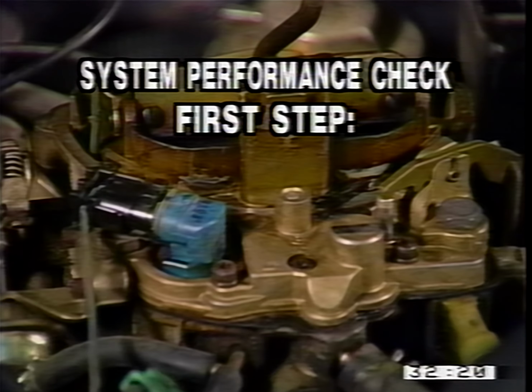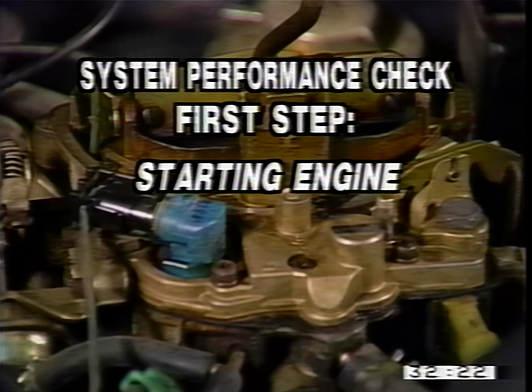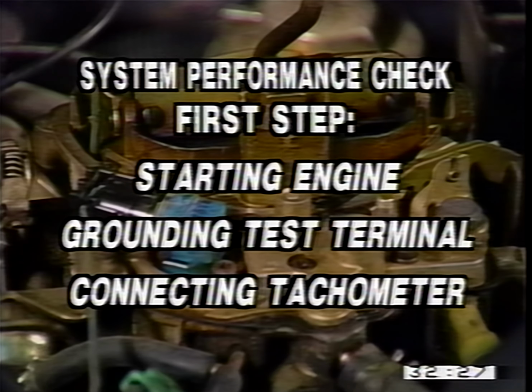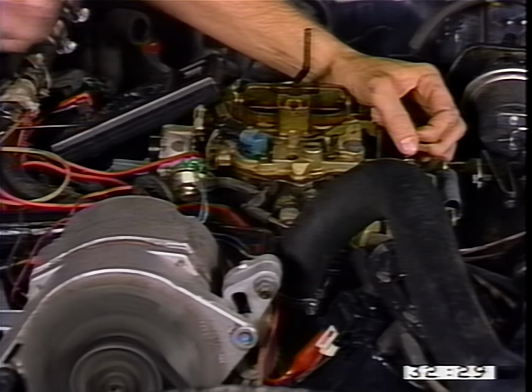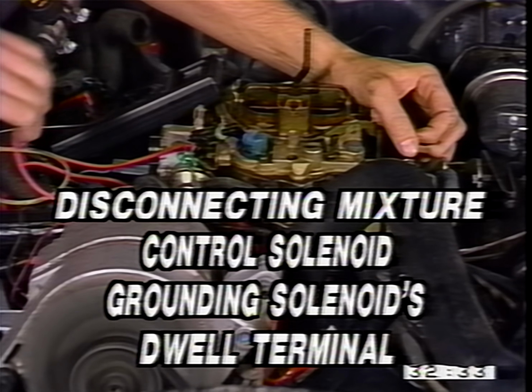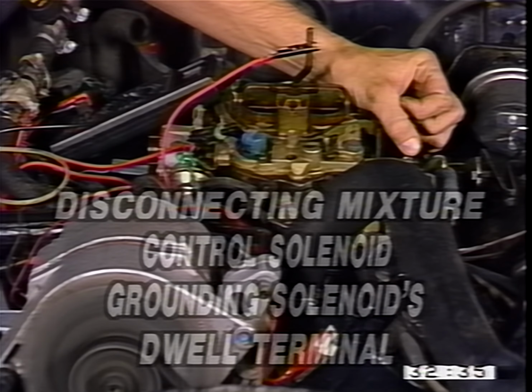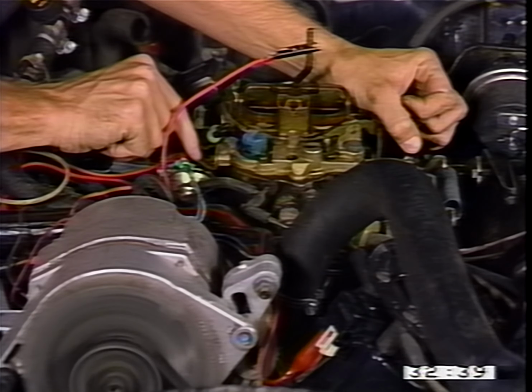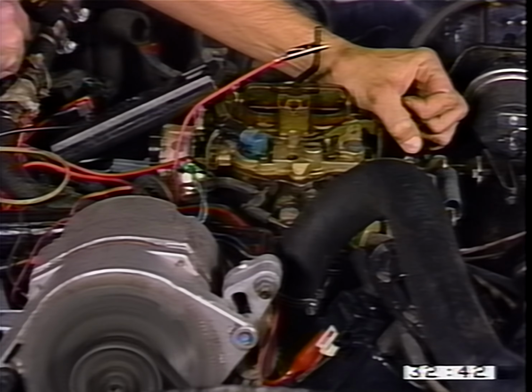The first step of the system performance check for full-function carbureted engines involves starting the engine, grounding the test terminal only while the engine is running, connecting a tachometer, and disconnecting the mixture control solenoid and grounding the solenoid's dwell terminal. The engine is then run at 3,000 RPM. The engine is kept at this RPM and the solenoid is reconnected.